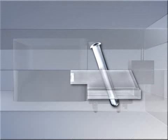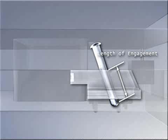The length of engagement equals the amount of distance the actuator pin travels within the slide block. The length of engagement and the angle of the actuator pin determine the amount of movement and force applied to the mechanically actuated slide.